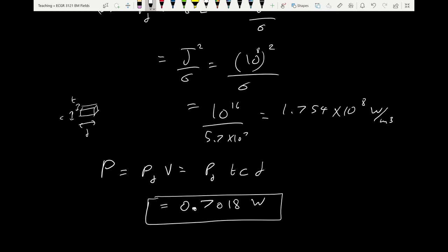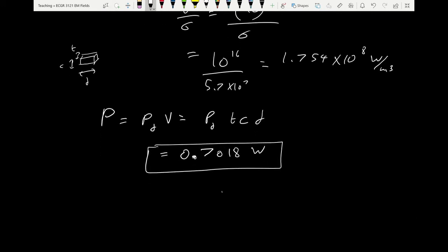Even if we are running at currents less than the protection currents for the fuse, the fault currents, we will get less dissipation than that, but there will still be some dissipation. Okay. So fuses are lossy. They will lose some power and heat up a little bit. We're sacrificing some of the efficiency by not maintaining the large cross-sectional area of the copper.